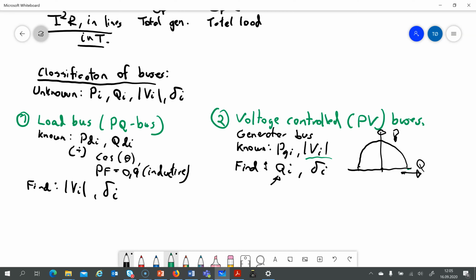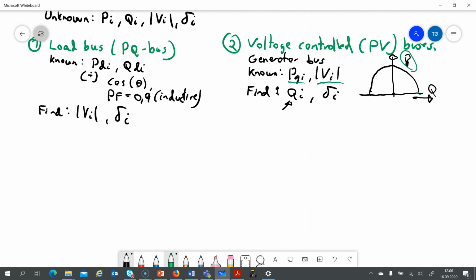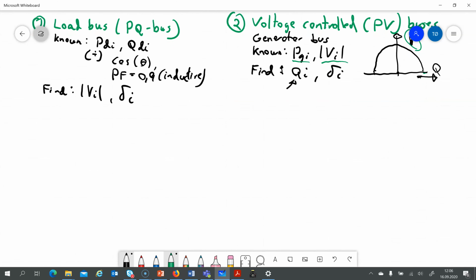Also for the active power, we can of course have that demand of the prime mover, the active power of the turbine. So that can also be a limitation here. That means that maybe if you can't get more active power, you need to transport it from another place, and then you will have losses in your system. That is something you have to think of, and you will then get, of course, a value for the mismatch and so on. The third is the slack bus.